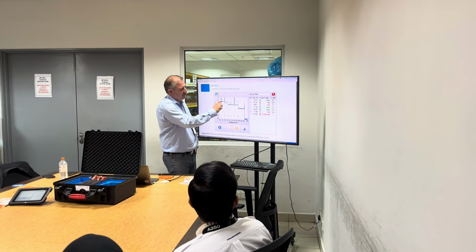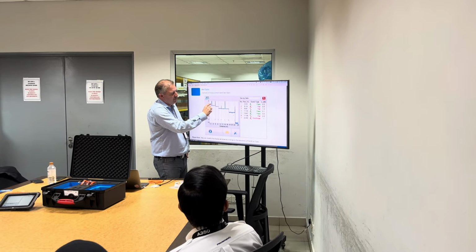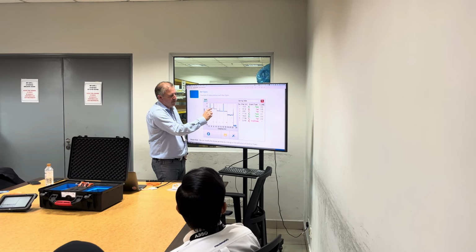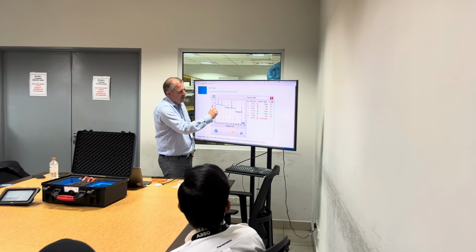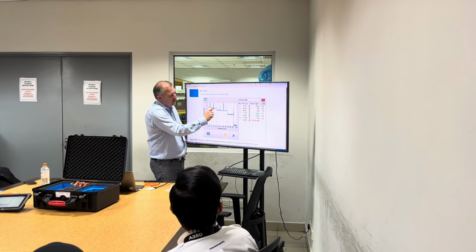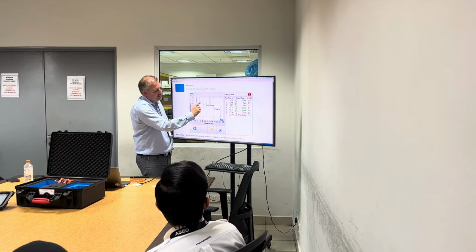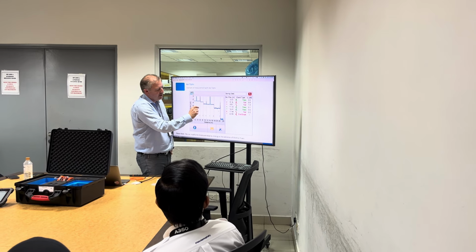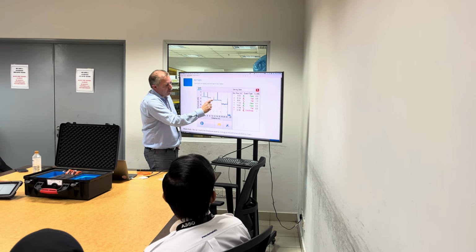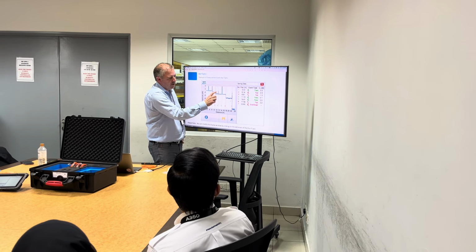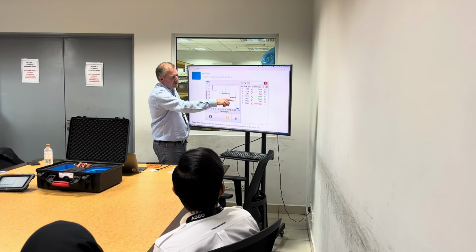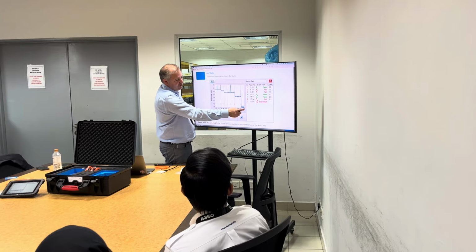It's pretty flat. So this is a connector with good performance because it's almost the same level of light before and after. This is a connector with some damage because I see the difference here is a little bit bigger. This is improper bending radius. This is most probably a loss, and so on. And you have all these events, and this is the end of fiber over there.